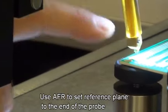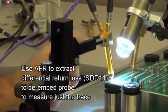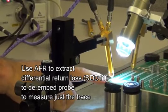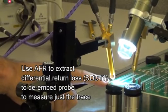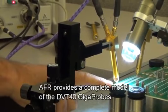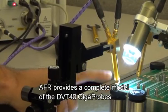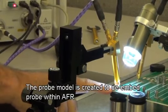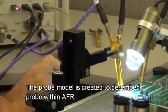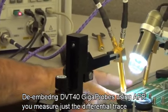We're going to derive the S-parameter model of the probe by using an AFR SDD11 measurement. And with that one reflect measurement, we're able to get the complete model of this probe and then de-embed that inside AFR and get just the measurement of the trace. So let's show how that happens.